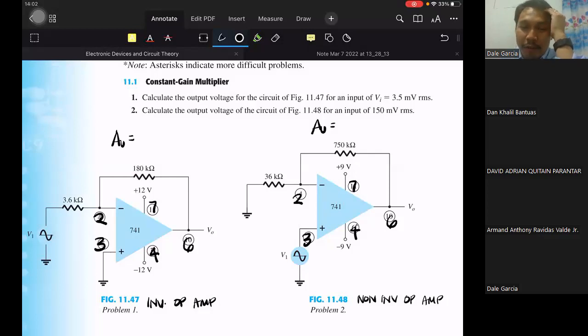Thanks for the link. Nice. It is a 14-pin DIP, dual inline package op amp. The output is pin 10, and the inputs are pins 4 and 5. Negative VCC is pin 6, positive VCC is pin 11. Pins 1, 2, 14, 13, 12, 7, and 8 are no connection. Offset null is pin 3 and pin 9, no?